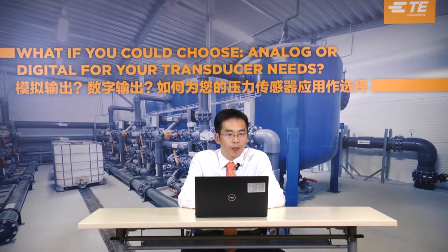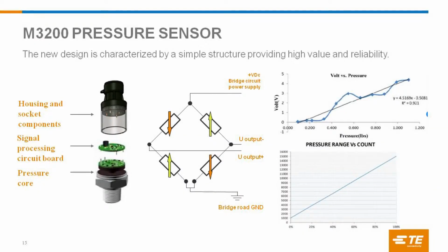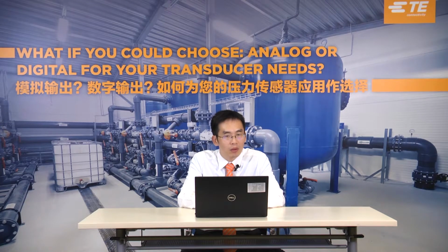It's an integrated modular design pressure sensor. It has the microfuse sensor core and a fully digital signal processing unit, and our housing is integrated with the connector and cable and all the EMC boards. With different customer demands, we can customize the pressure port, the pressure range, and output signal with those modules.